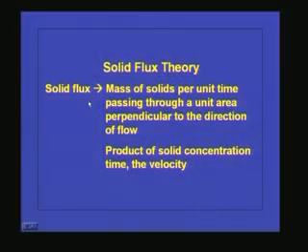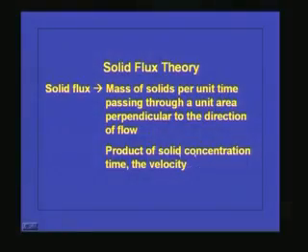Solid flux is nothing but the mass of solids per unit time passing through a unit area perpendicular to the direction of flow. That means the mass of the particles passing perpendicular to the cross sectional area at a given time is the solid flux. Whenever we talk about a sedimentation tank which has a constant underflow, the flux will be because of the underflow velocity as well as because of gravity. So, we have to consider both together.